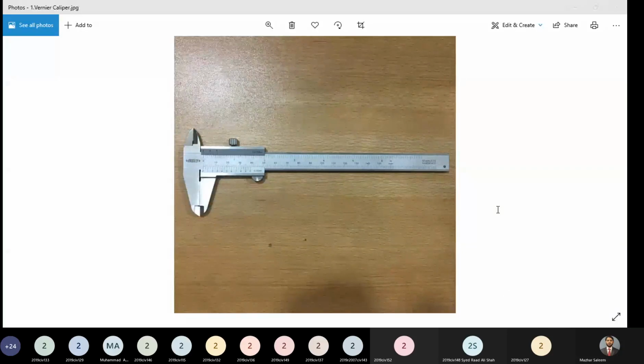External diameter, we will use outside calipers. But even then, that uncertainty is there. So we will have to take the reading cautiously. That's the only thing I can suggest. It depends upon the judgment and care of the person who is using the device. These inside calipers and outside calipers are not sophisticated instruments. If you want a really precise measurement, then preferably you should not use them. But in some cases, we need relatively crude measurements. Only in those cases we use these devices. Okay, is it clear?